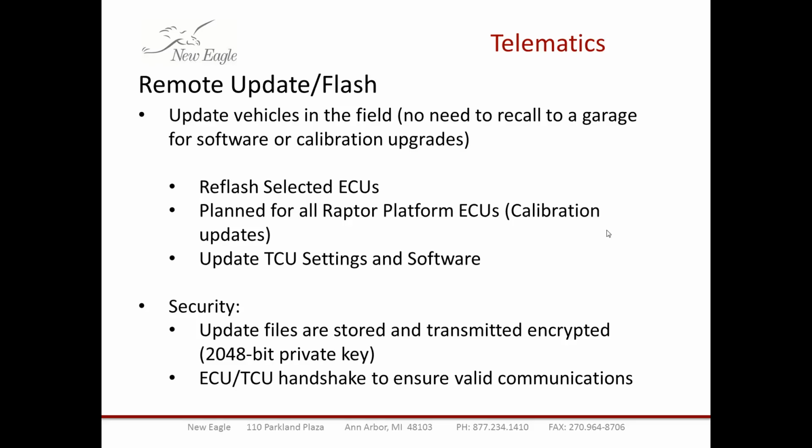So in order to provide some security for that, as soon as a file is uploaded, it is encrypted using a 2048-bit private key, and the files are stored and transmitted in an encrypted format, and they're only decrypted once the TCU is ready to apply the update. So even when the TCU caches it, it caches it in an encrypted form to make it as difficult as possible for somebody to intercept that and possibly compromise your IP.